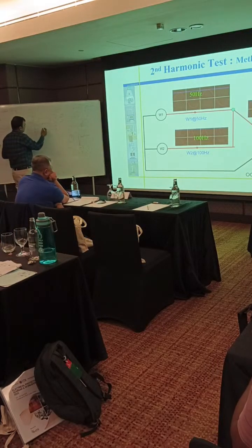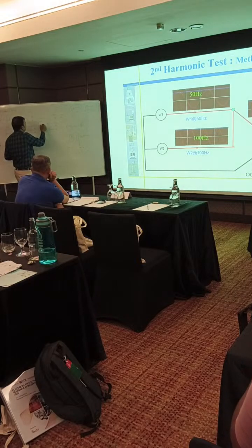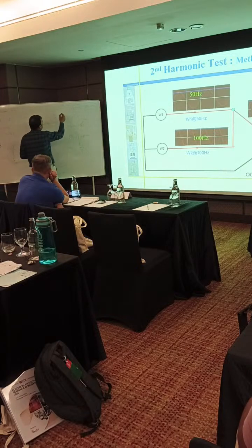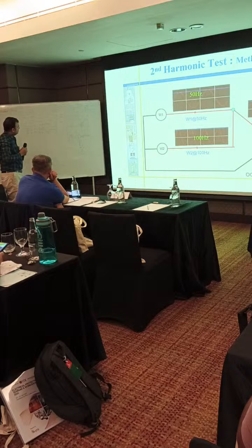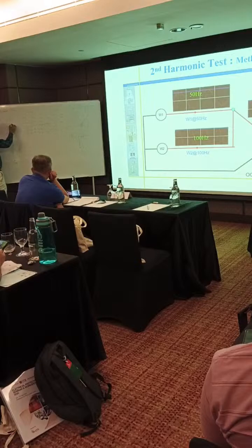So as I said, there are 3 differential components here. Whatever the differential current is, the operating current is already present in this. The relay is blocking just due to this harmonic component. We reduce this value, so it will trip when it is less than 20%.